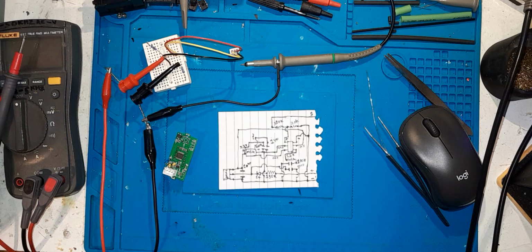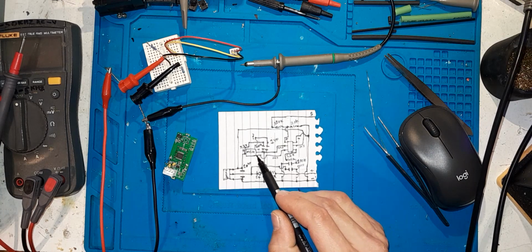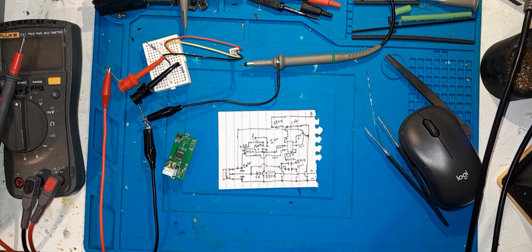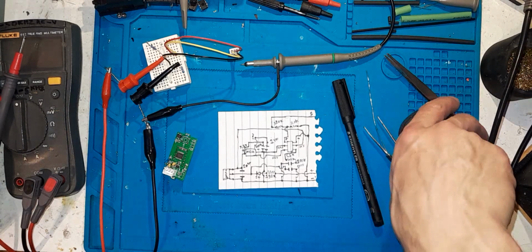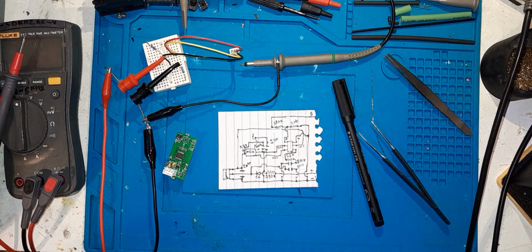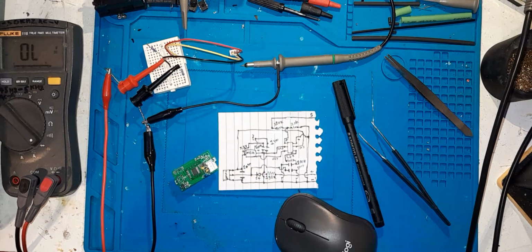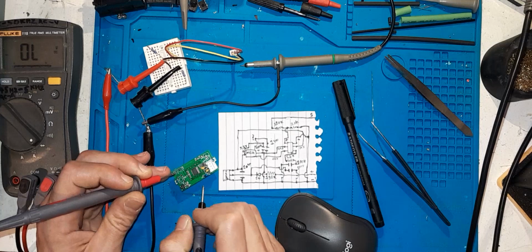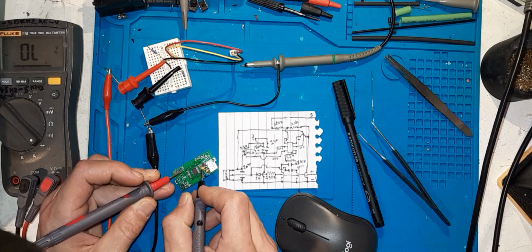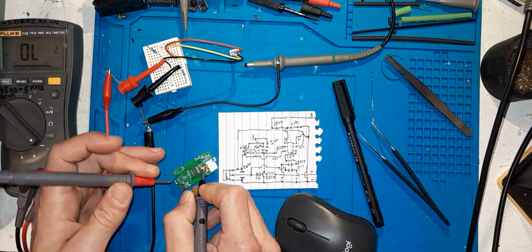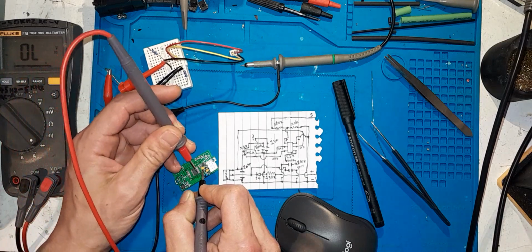I'm going to go have a look in the data sheet and see what this input is, because that will tell us if it's a DAC input or if it's a GPIO input, or what sort of input it is. I'll pause the video and I'll go back to the data sheet, because I still want to skim through it and find out the calculations for VCAP, and I want to know what that pin is right there. Alright, I'm just going to quickly measure exactly what pin the output of this 6-pin device is on is going into.